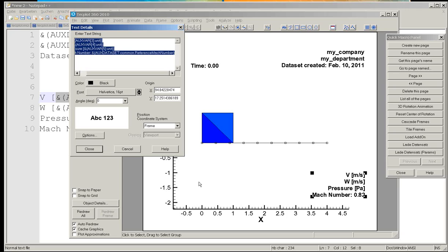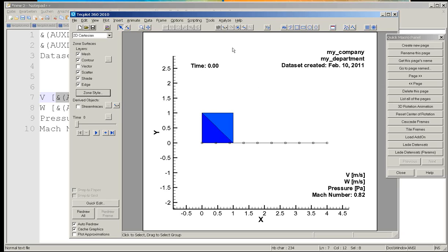Well, my recommendation is output as much information as you need into the Tecplot file, and then use a style sheet, or you can also use it within a layout file to place your information onto the frame. That's just one purpose. The other purpose I mentioned is the presettings for the analyzer.